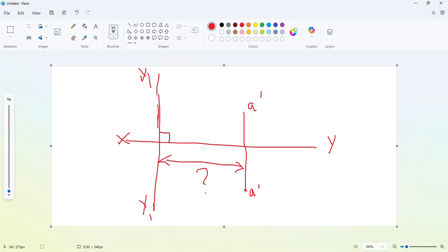Okay, now the next step is again a similar thing. We have to plot the side view, the right view, so the projection will be on the left projection plane. So this reference line will be on the left side of this projection. Our next step is, from this point of intersection between X1 Y1 and XY, both of which are perpendicular to each other, you have to create an inclined line at 45 degrees with the XY line, and the direction will depend on the direction of the top view.